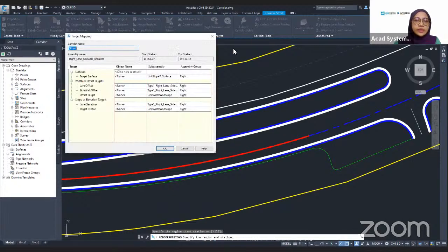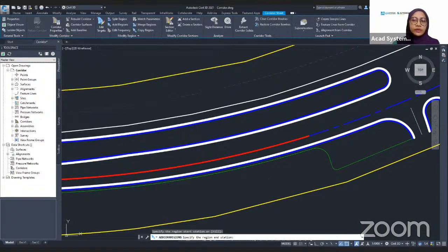All right, so this will continue using the same target surface here, existing ground again. For the lane offset, we can just put it similar to this line. Otherwise, for the sidewalk offset, I don't want to put any because now we don't have the bus stop shape. So just click on OK from there, and that will post it my new road junction.